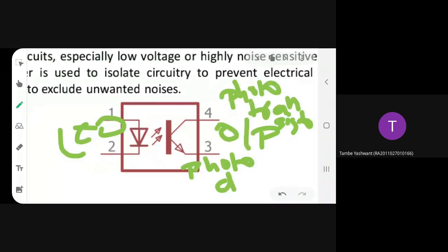Ma'am, what is a noisy circuit? Noisy circuit means, suppose you assume your single phase AC supply is of what frequency? 230 volts and 50 hertz. Suppose the output that is coming out does not belong to 50 hertz, it has some other frequency superimposed on that signal. Then you will hear a small amount of hum. Have you heard that hum sound? There are many different types of noises. You should not have that unwanted frequency component mixed into the wanted component. Those components are called noise components in general.